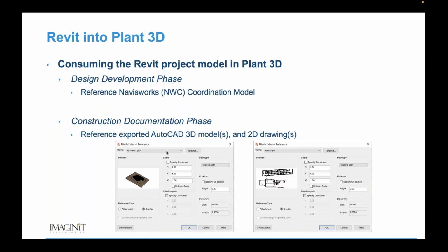Worst case scenario, as I said, we can have Navisworks running in tandem with our design tools with that federated model open, and then as I make changes to the design, that federated model will also show me the changes. But again, that isn't going to be sufficient when it comes time to create those projected views that incorporate both the 3D process information with the Revit structural or architectural information that you have in that model.